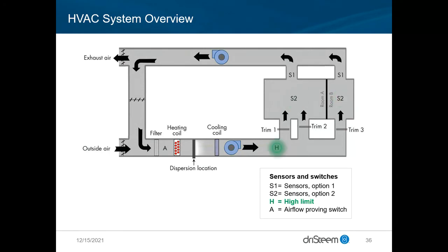Want to also talk about safeties. Those are very important, especially your high limit. This is to make sure that we don't over humidify, whether that be from changing air conditions from the outside. If outside air dampers are open quickly and masses of air drive up humidifier requirements, and then they close, if you can't change your humidifier level quickly, you're going to be over humidifying and wetting the ductwork, and that's definitely what we want to keep away from.